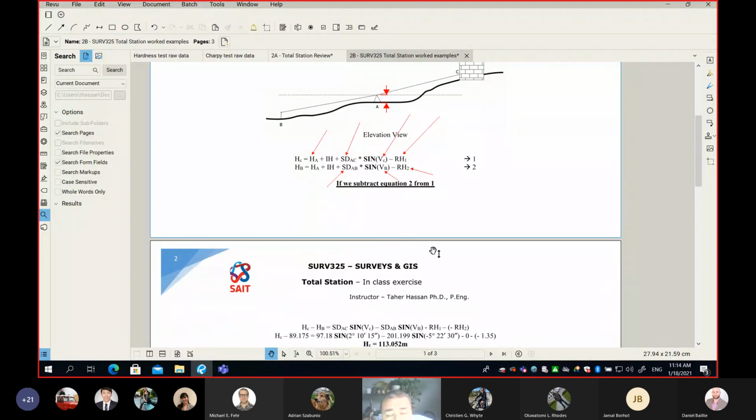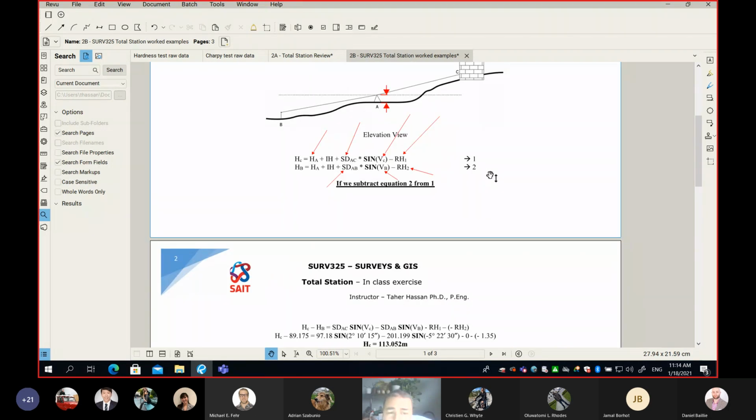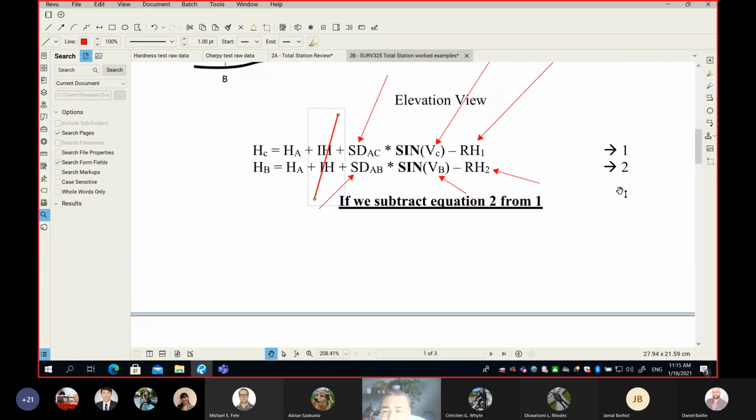But listen to this, please. You guys know from mathematics that if I have equation 1 and equation 2, am I able to subtract equation 2 from 1? Go ahead and say what equation 1 minus 2? Yes, you can. Mathematically, you guys know that. I think you have enough math to know that. And guess what? If I subtract, because IH in equation 1 and equation 2 are the same, since my total station never moved, it is the same setup, which means the instrument height is the same. And this means even if IH is not known, when we subtract equation 2 from 1, those will cancel each other.